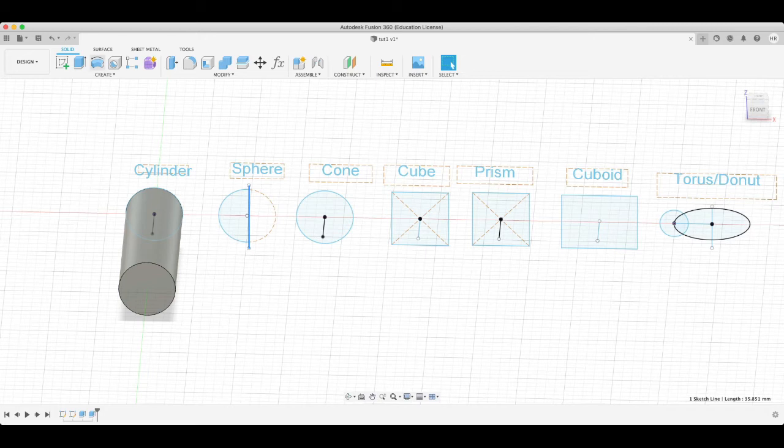To make a sphere, we'll use a different concept, slightly different but similar. Instead of the extrude, which is on the top left, we use the next one to it, which is revolve. It's quite similar to the extrude, but however, instead of stretching the object, so to speak, in a straight line or in an axis X, Y, or Z, we'll be stretching it around an axis.